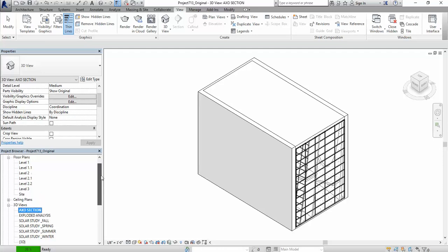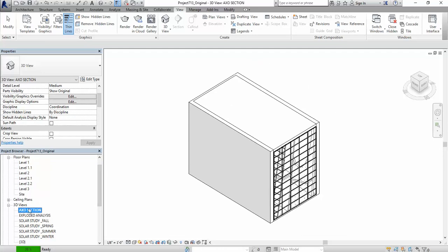Nice. And that's a very, very easy drawing. So as soon as you have highlighted the view, you can go under the properties of the view, under the extents menu, all the way down. You should have the section box option.